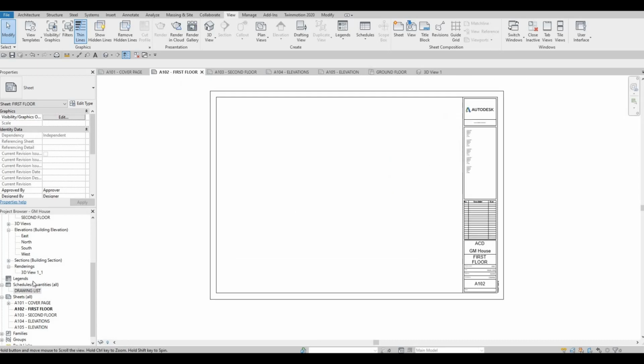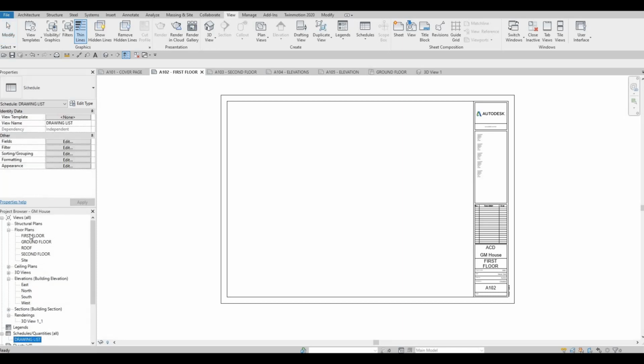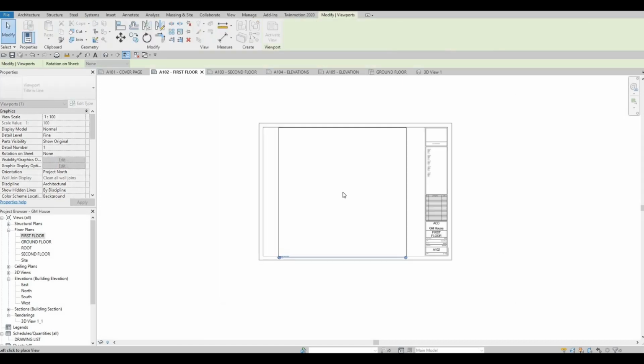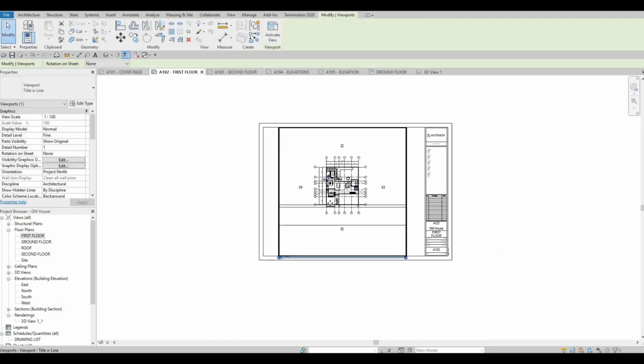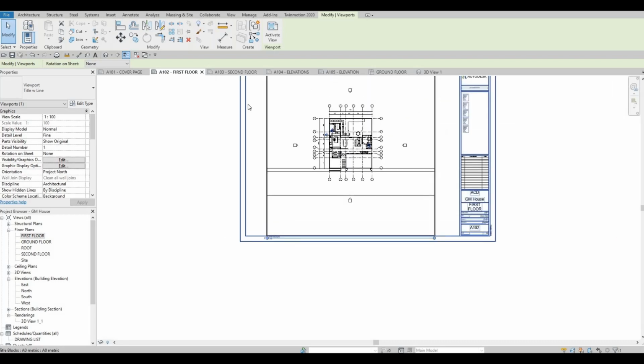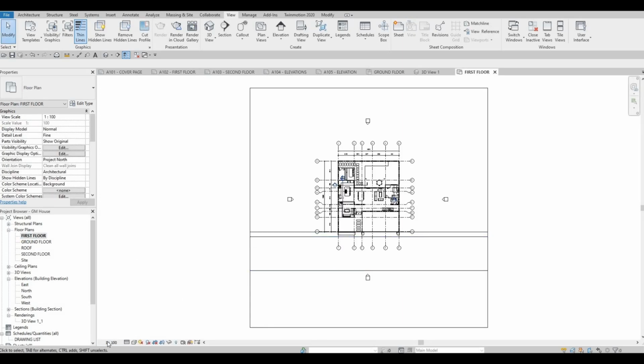And as you can see, it's blank. So we're gonna simply drag and drop it. And for now, we're gonna see how it looks. It looks small. We could increase it. So right now, the standard is 1:100 on metric. So we're gonna delete it first and then go to first floor. Here in first floor, what we could do is increase it by 1:50.